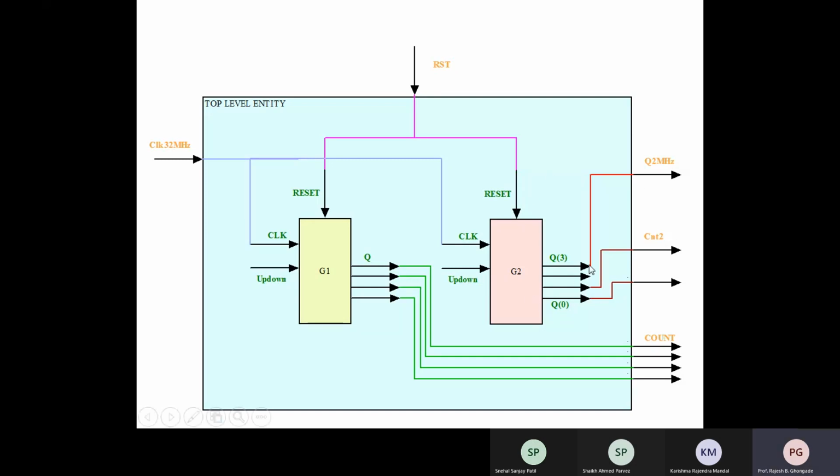Yes, sir. And when will this bit change? Up, down, up. When will Q3 be high? After how many clock cycles? 8.